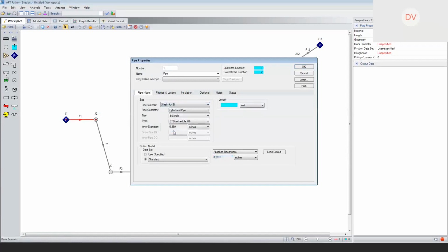What that allows us to do is get into our standard units for the imperial units, and we've identified the 30-inch line as our starting point for the diameter. And we're going to always use standard wall thickness, which translates to 0.375-inch wall thickness. So this is the inner diameter, so it's the 30 minus the 29.25 divided by 2. That's your 0.375.